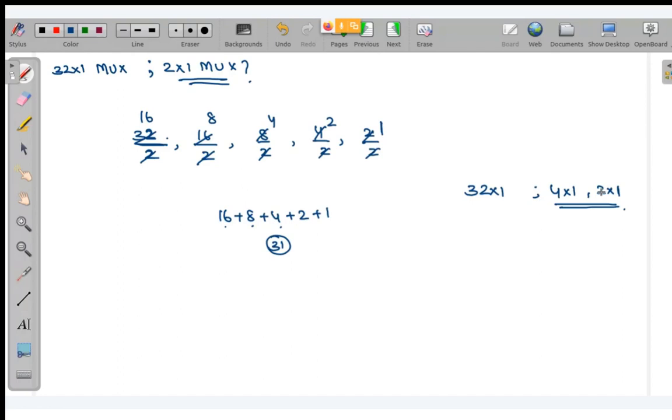Chandana is telling. So look over here. You need to divide this 32 by the largest available mux you have, that is 4. So divided by 4, what do you get? 8. Again you can divide it by 4, so you get 2. Again 4 you can divide it by 4, so that will be 1. So you will be requiring 8 plus 4 plus 1, so 13 mux will be required.